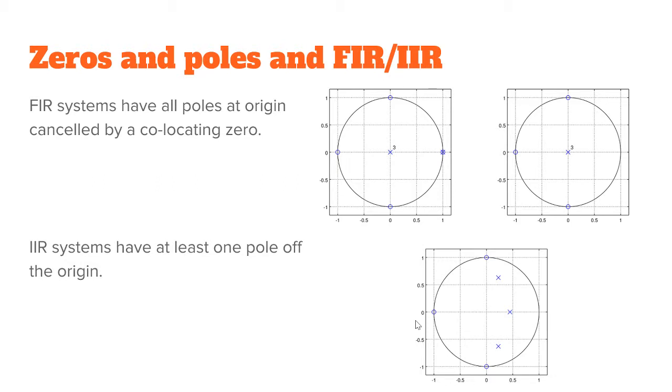I think last time in the classroom we already found out, okay, the 4-point running average filter has the zeros here and poles here for this representation, but for the feedback representation we had also one pole here and a canceling zero at the same spot, meaning that it's still FIR because these are cancelled out and all the poles are otherwise on the origin.